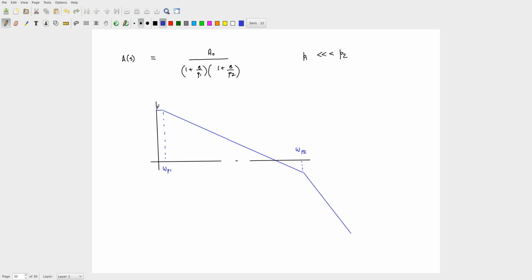All right. Now, what is this quantity? Let me say this is just A of S, and we just discussed that your worst case operation is when k is equal to 1. So, if k is equal to 1, what can you tell me about open loop gain and the loop gain? Same, right. So, k equal to 1 implies your A of S is identical to your L of S. This is your open loop and this is your loop gain.